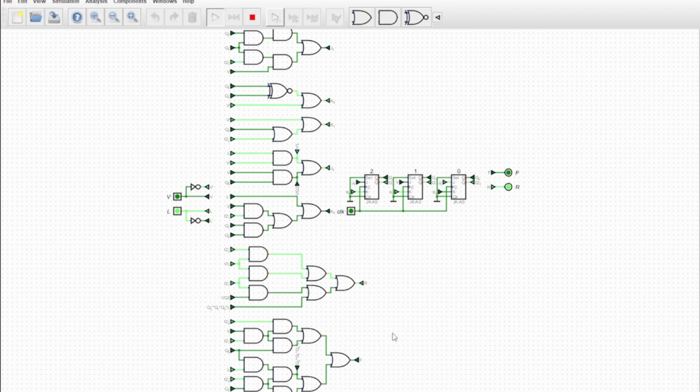But after talking with stakeholders, I realized it was unnecessary hardware to incorporate, as we simply don't care about glitches in a design like this. It's not really an issue if there is slight interference in the signal, because it won't really impact the output of the pumps in a significant way. So I forewent those. So these are going to immediately update without a clock tick.